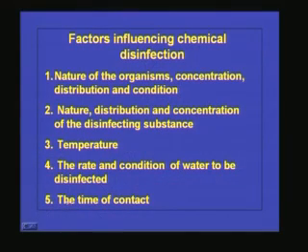So, the microorganism will not be getting exposed to high concentration of these chemicals. So, naturally the disinfection will not be proper. So, if you want to have a high efficiency of disinfection, the water whatever we are subjecting for disinfection should be clear of turbidity, organic matter and other pollutants. And the last thing is the time of contact, because if the microorganisms are getting exposed to a toxic compound for longer time, definitely the rate of kill will be more. So, time of contact is also very, very important.